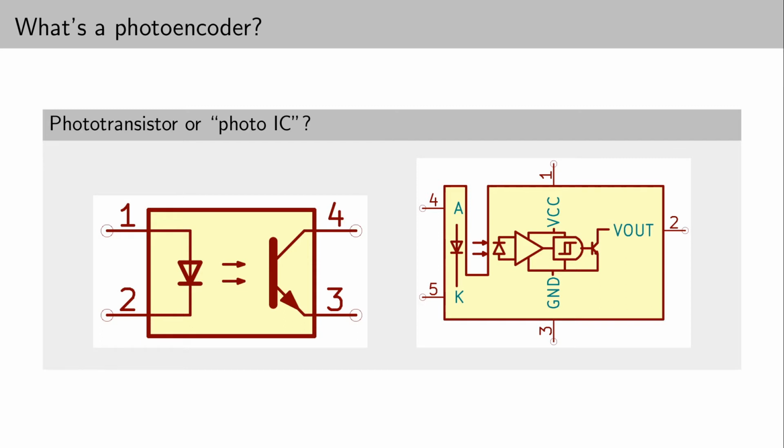We're going to be going between completely occluded and partially unoccluded, which means that we'll need to be careful about setting the threshold for the comparison that goes on here. So I think we're going to be using a phototransistor kind of photointerrupter and developing the circuitry that goes on this output ourselves.